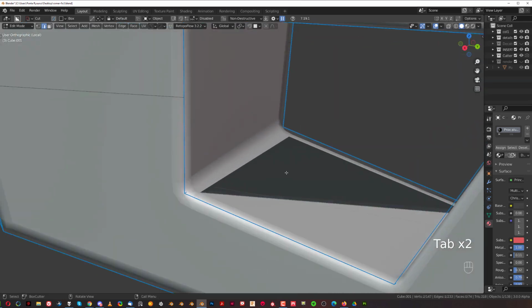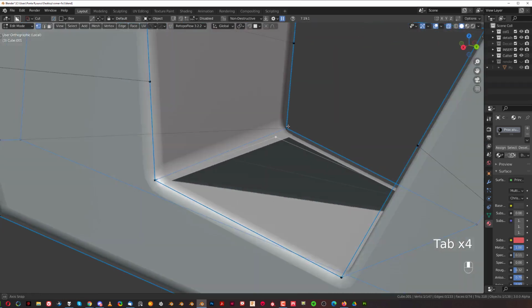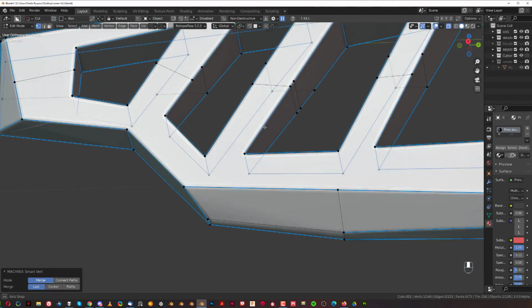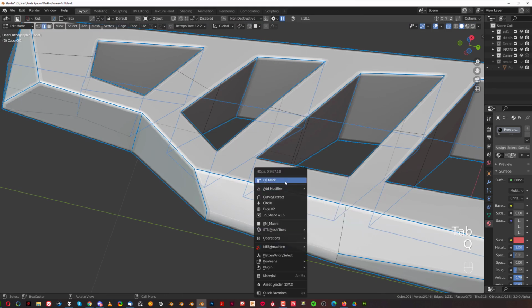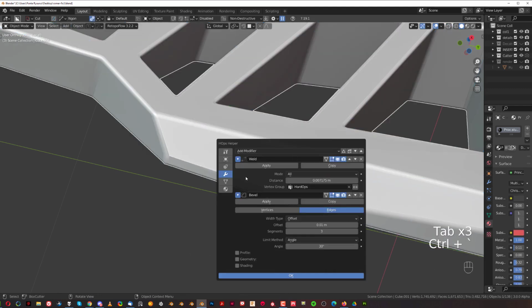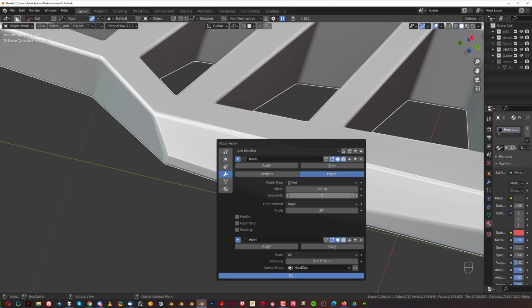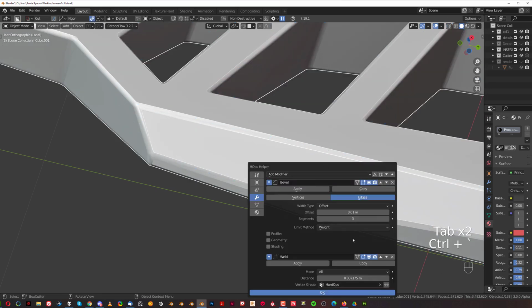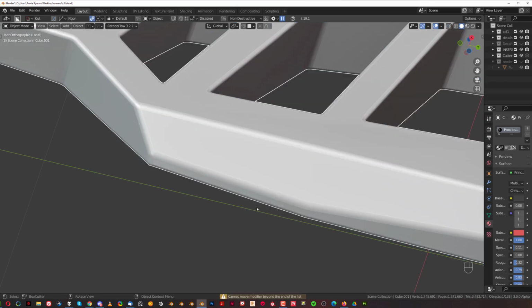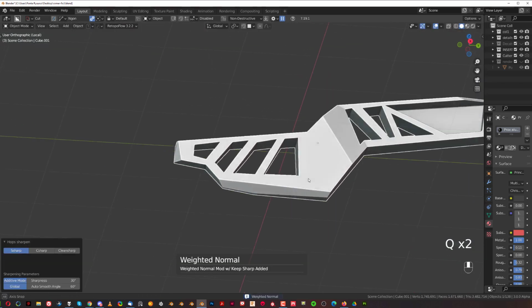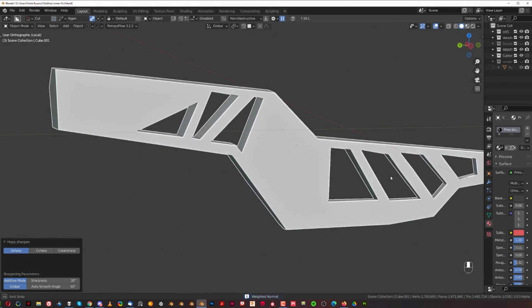Wonder what's causing it. Let me go to occlude. Ah, that's the problem. Boom. Sorted. Right. This one should be sharp. And we could technically change this to bevel, you know, because the bevel doesn't catch the angles really very well, so we could change it to weight like that. And I don't think we need weld. We remove the weld. Bevel's a little bit too crazy, and we're gonna apply weighted normals. And there you go, that's your fixed piece.